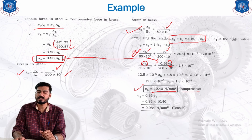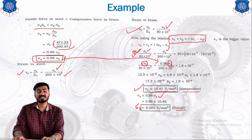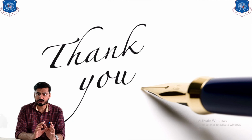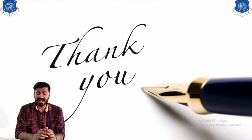If you put this value in equation number 1, then you will be able to calculate the value of sigma S. Sigma S is nothing but the stress of the steel material, which is of tensile nature. So this is how we calculate our example. All you need to do is remember the two steps that we use to calculate the example of a composite bar subjected to thermal stresses. So this is the application of thermal stress in the composite bar.